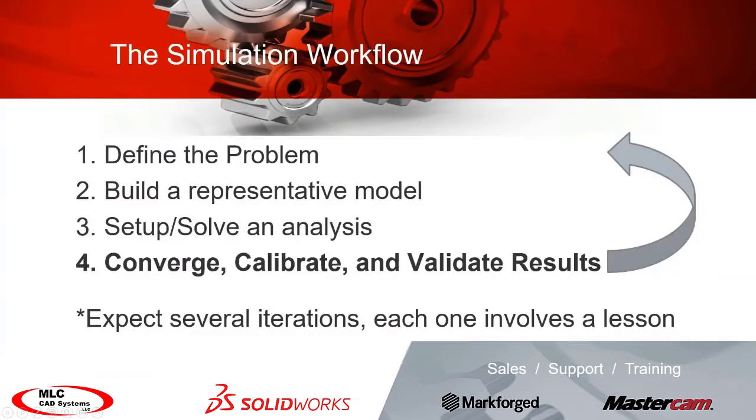Now, when you're running simulation software, it's a pretty basic process, right? You want to define the problem. What are you trying to figure out? You want to build a representative model, and using SOLIDWORKS, it's very easy to put something together, and then you'll set up an analysis and run it. And that study will capture all the things that you know, and then you'll find out what the answer is. Now, the focus of this video, though, is the Converge, Calibrate, and Validate steps.